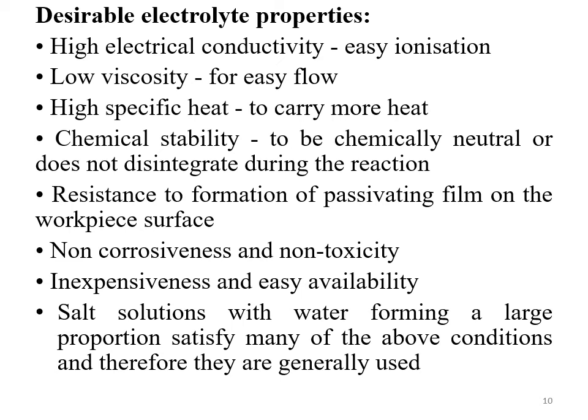That's why highly viscous fluids are not preferred here, or high concentration fluids are not preferred here, whereas the electrolyte needs to possess a very low viscosity so that it can easily be pumped to the machining zone.